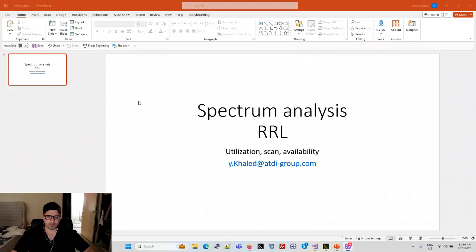So today I have a new video, and that video will be looking at spectrum analysis using the RRL plugin, which is based on the RRL database, which is an Australian spectrum database. I'm going to demonstrate how you could use the plugin to do some channel reuse analysis, like spectrum utilization. We're going to do some spectrum scanning, display signal level predictions, it's all based on predictions, and conduct some availability analysis and so on.